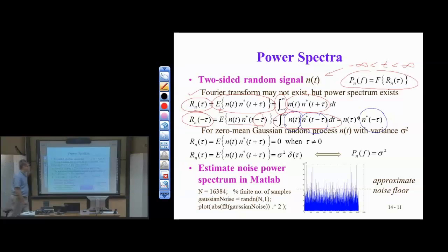Again, in autocorrelation we hold one signal in place and slide the same signal across, instead of flip and slide. That's correlation. To make convolution behave the same way, we have to flip the second argument, so that when it goes through the convolution formula, it gets flipped back to where it was, and we end up with just a slide instead of flip and slide.